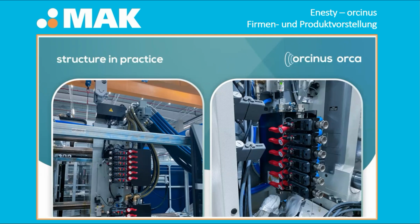Here you see that there are two different pairs of hoses coming to different manifolds. This could mean that the customer wants to have different temperatures at the mold, which is very common. And so from different TCUs, you can manifold different temperatures. So every manifold gets its own hoses. So I think this is a different temperature.